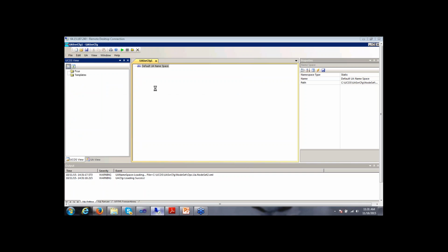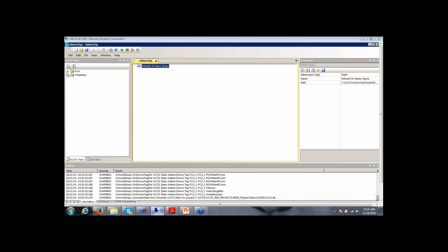And once that process is complete, you're able to see here in the window, we've got 4 templates, a choke, a valve, an analog instrument, and a digital instrument. Under each is the instances of all those templates. So these were created by connecting it to an actual subsea system and importing these.